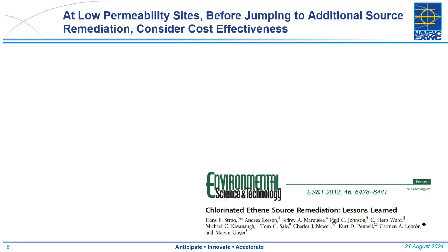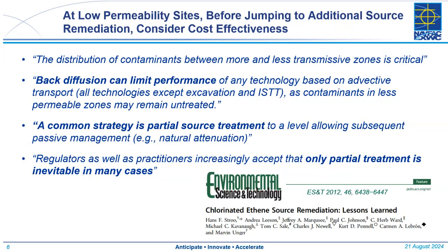About 10 or 12 years ago, a paper was published by a team of experts in the journal Environmental Science and Technology. They looked at this problem of chlorinated solvents diffusing into low permeability deposits, and drew some interesting conclusions. One, back diffusion can limit the performance of any in situ remediation technology. The only technologies that would always work would be in situ thermal treatment or excavation. But because of back diffusion, we have this problem of getting to 100% cleanup.